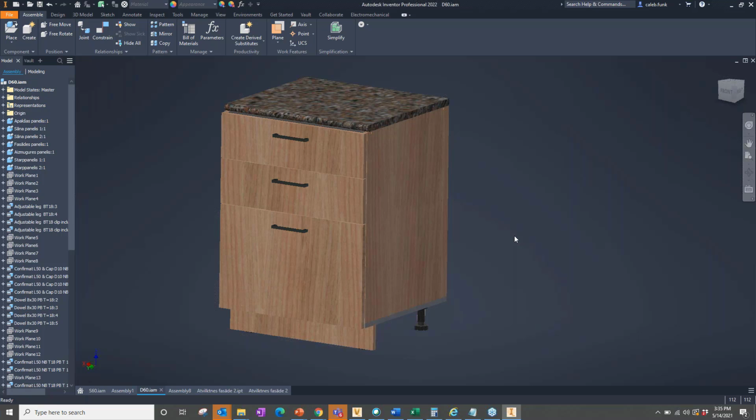So I mentioned there was the idea that it started as a Revit family. I said those words, and that's kind of a collection of items within Revit. It could be doors are a Revit family, windows are a Revit family. Casework like this is a Revit family. And I have the ability to send this right back as a Revit family. So that's something that I can begin working with, and I can bring that information in.